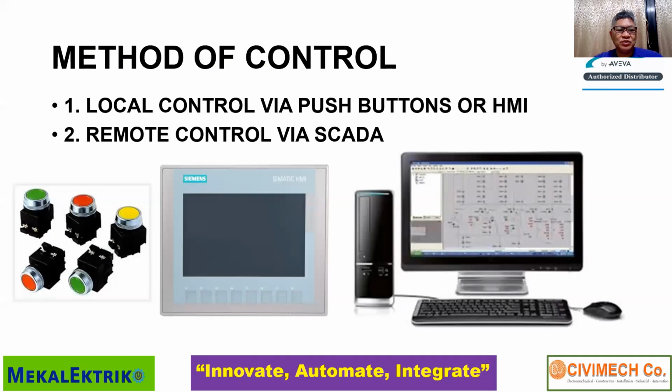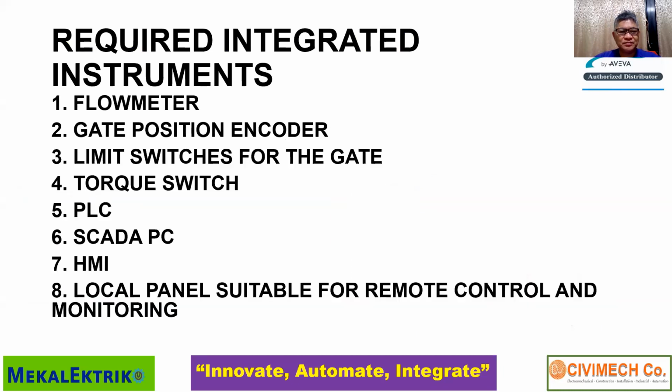The method of control, normally for dams and for big sluice gates, is using local control via push button or HMI. Most of the time in today's industry 4.0, it is remote control via SCADA, supervisory control and data acquisition.